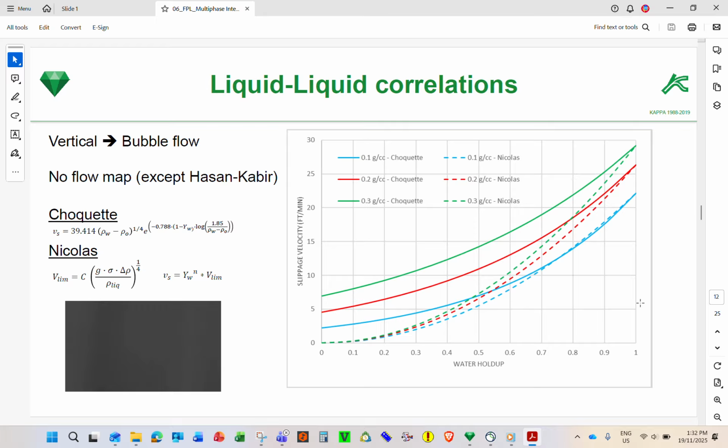Yes, in the instrument we do that. We have in the multiprobe tool processing some calculation. With the camera, you can see the size of the bubble, and you might estimate the bubble size at maybe 5 millimeters or so. Then you can detect the number of bubbles. Remember, you have the needle, right? The bubbles are going into the needle. So in 1 second, maybe you have 100 bubbles. So we just estimate the rates.